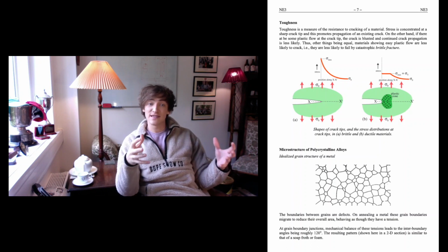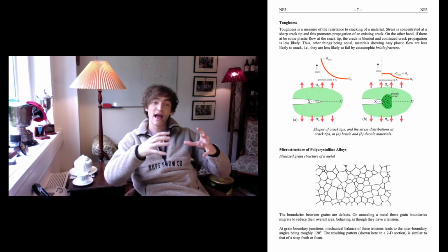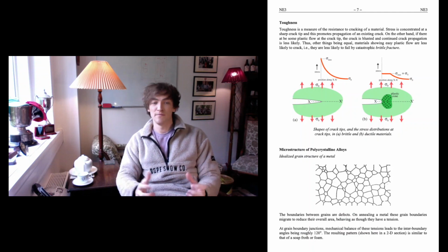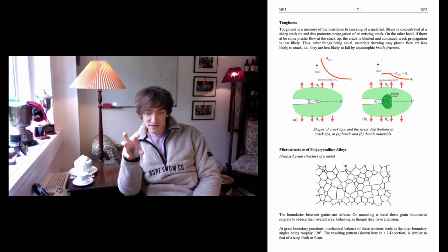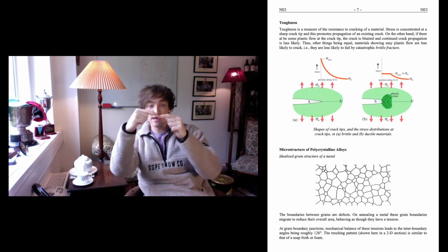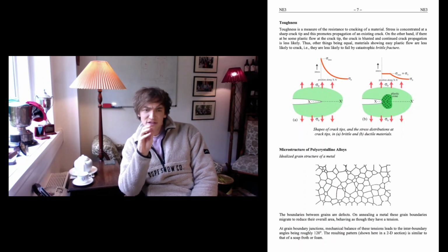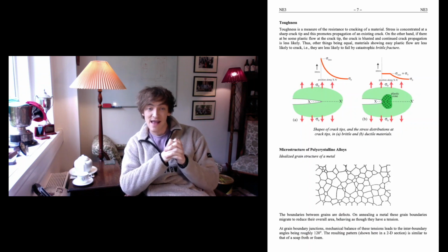Yeah? So the material is effectively reducing its defect density by growing the grains, and in doing so, reducing the grain boundary area per unit volume. Now, if you were to look at a grain boundary junction, i.e. where 2, 3, or 4 grain boundaries meet, the tensions mechanically balance and cause interboundary angles to consistently be around 120 degrees.